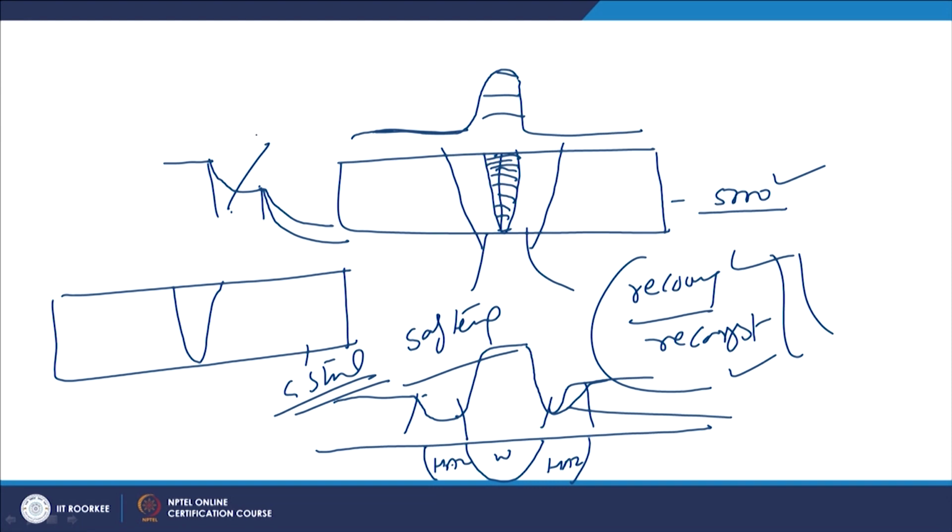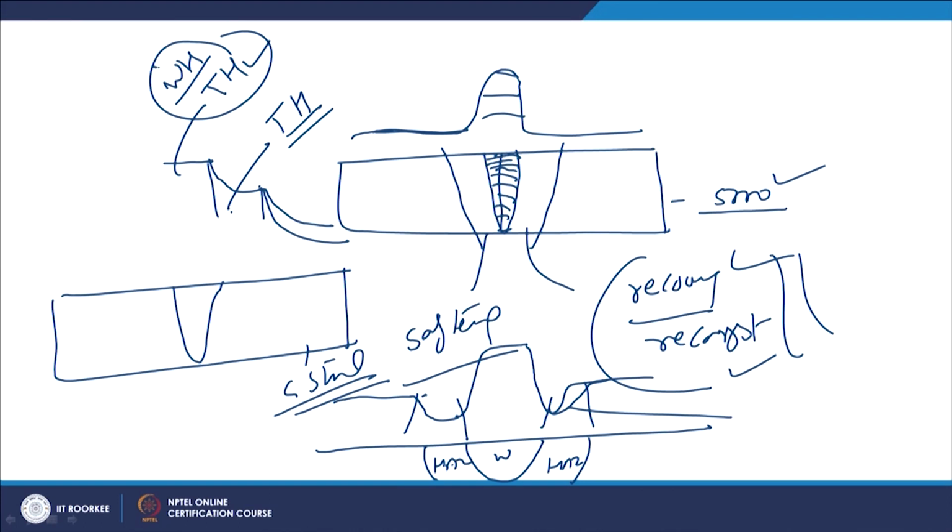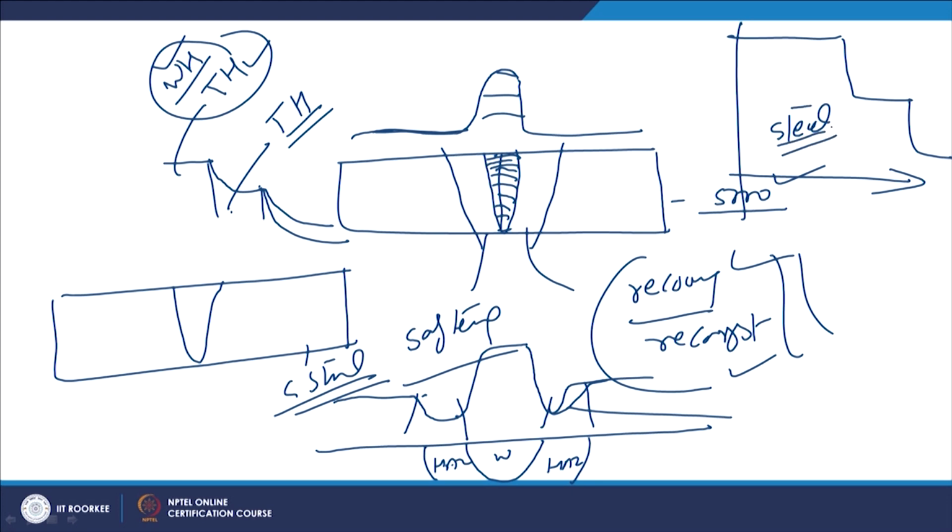So, this higher hardness in case of hardenable steels, wherever transformation hardening is involved, can be attributed to the transformation hardening, while in the weld nugget it may be the combination of work hardening as well as transformation hardening, because a lot of heat is generated coupled with the plastic deformation. So, that causes transformation hardening as well as work hardening. So, we may have the maximum hardness in the weld metal, then somewhat lower hardness in the heat affected zone, and further lower hardness in the base metal, and this kind of trend can be there on both sides in case of transformation hardenable systems like steels, when they are subjected to solid state joining involving plastic deformation.